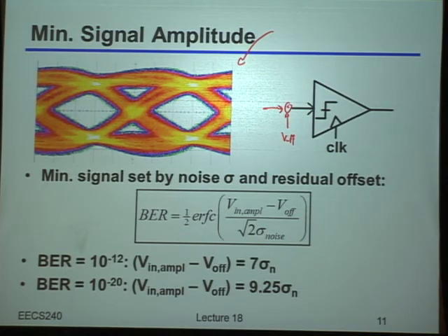That's certainly possible. As we'll talk about more later on down the road, though, even if you put two transistors right next to each other, and you do everything around them to be exactly the same, they will never be exactly the same in terms of their characteristics. There will always be manufacturing-induced random variations that will cause this offset to occur. Now, having said that, on any one given chip, once you've fabricated the thing, largely speaking, that offset is fairly constant. So if you mean deterministic in the sense of not varying in time, that could certainly be possible. But from one chip to another, you may not be able to predict what the value of that offset is. And we'll talk some more about that later on down the road.